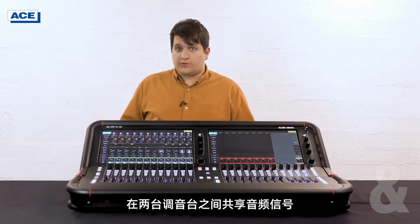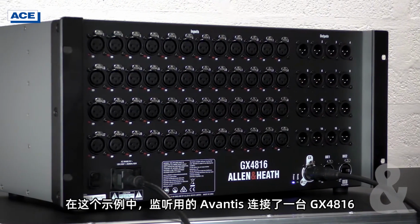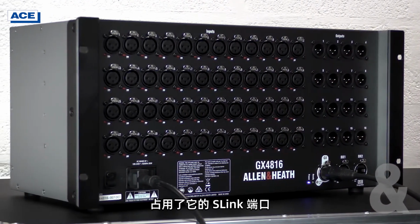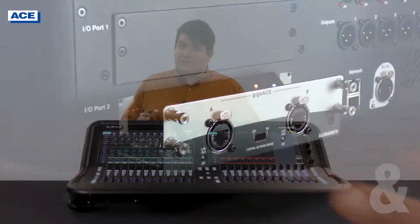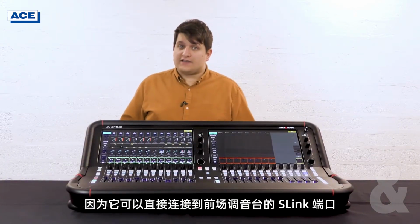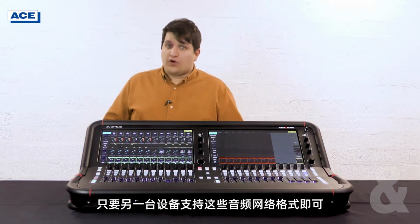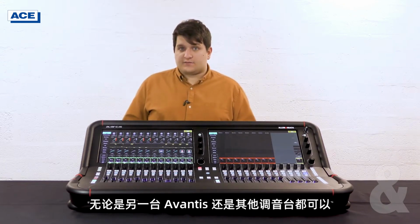To start with, we're going to need to decide how we're going to share audio between the two consoles. In this example, our monitor Avantis has a GX4816 occupying its S-Link port. We're going to need to add a card to one of the I/O card slots to share audio from the console. In this example, I'm going to use a Gigarace card, as this can be connected directly to the S-Link port on our front of house console without any additional equipment. However, you could use MADI, Dante or Waves if the other Avantis or indeed any console supports these standards.